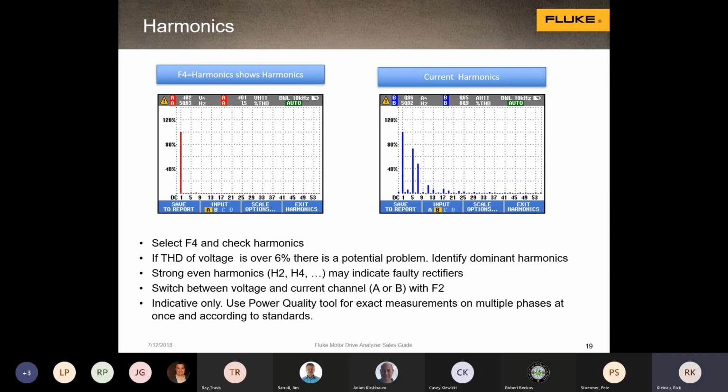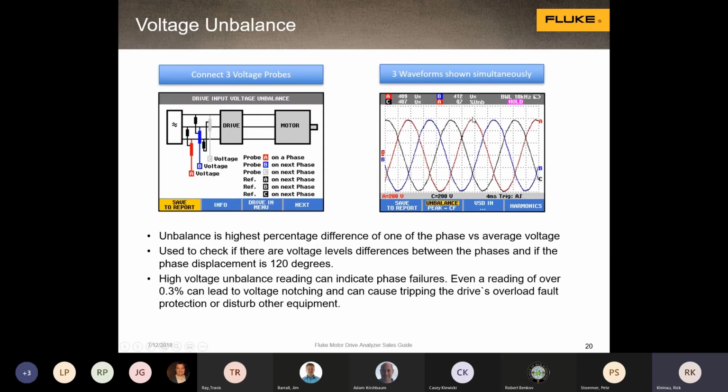Again, this is something you can do with any scope meter. They have a fast Fourier transform. They can do the arithmetic to give you the frequency domain graph that is the harmonic screen here. But on a regular scope meter, it doesn't give you harmonic numbers and nice clean bins. It would look more like a spectrum analyzer. But this also calculates the THD for volts and amps.